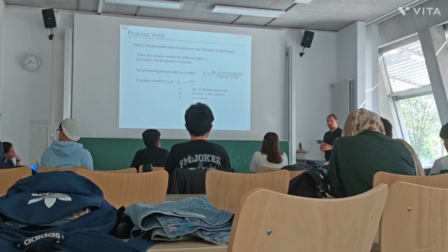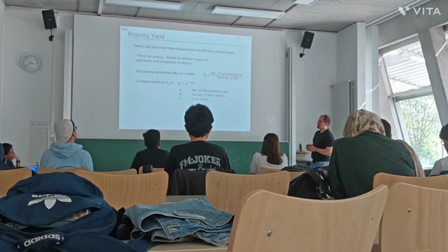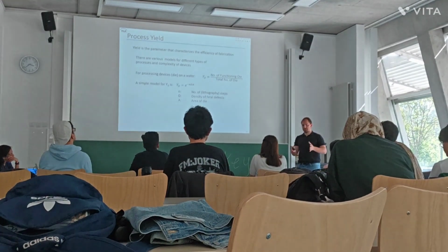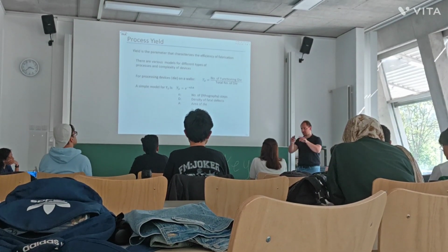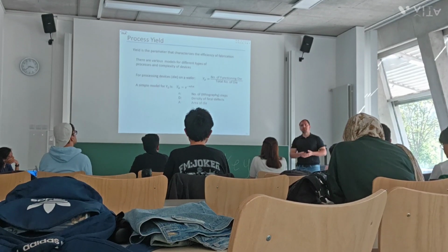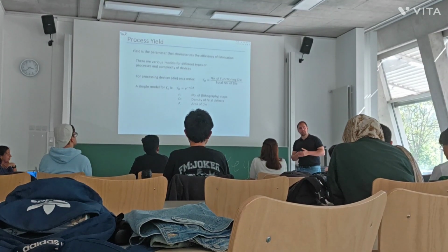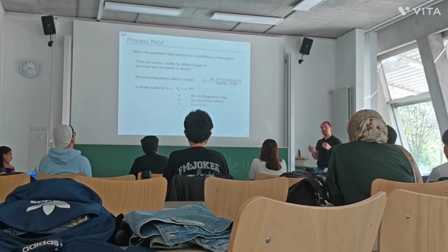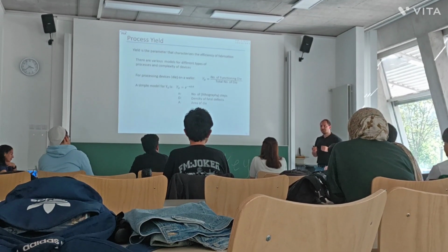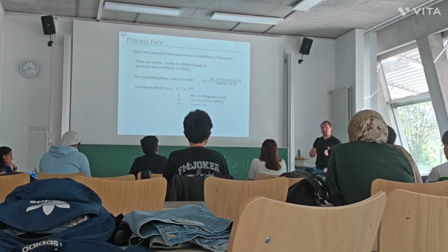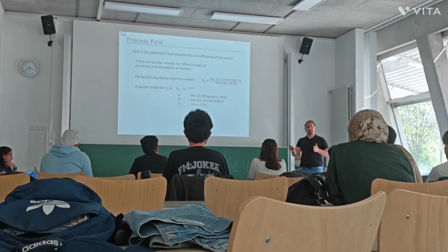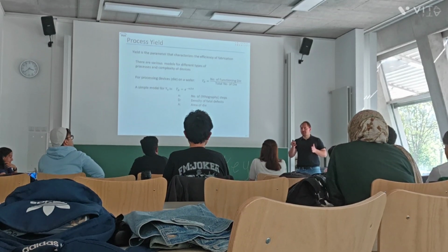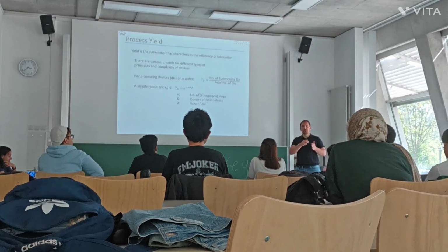We work mostly in MEMS devices. So when we have our MEMS device, we, let's say, fabricate 10 million on a large scale. 8 million of them work. We know 8 million divided by 10 million, 80% is the yield. In university, the yield is not the most crucial thing, because we are mostly interested in the proof of concept. So when we fabricate 100 samples and 2 are working, and they show the principle, the proof of concept is fulfilled.